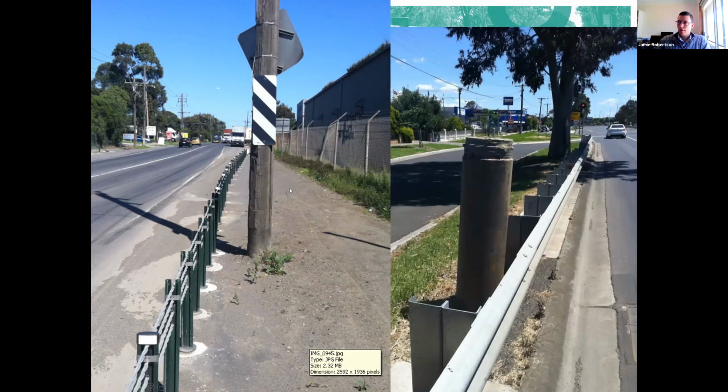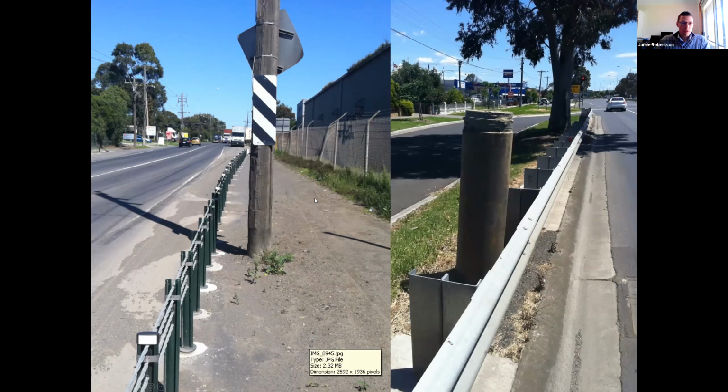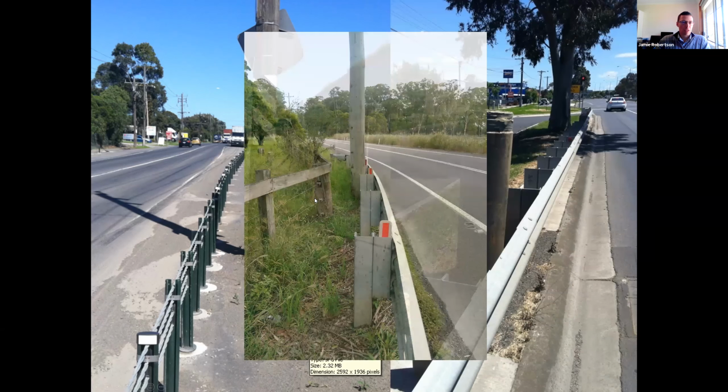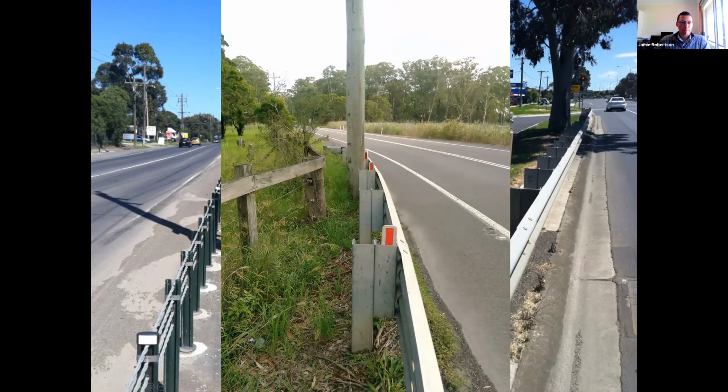as could that asset. And this pole, obviously, it's nearly touching the barrier. It's a power pole. You probably haven't got a hope in hell of relocating or undergrounding it. It's simply too costly. So in many cases, we just have to do the best we can by stiffening up the system. And you can see that in this case, it's a tri-beam system, so it is a stiffer system.